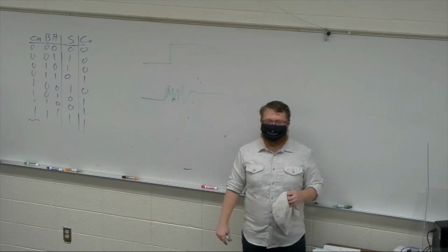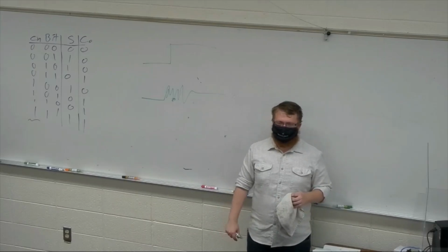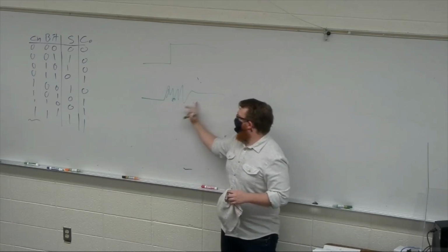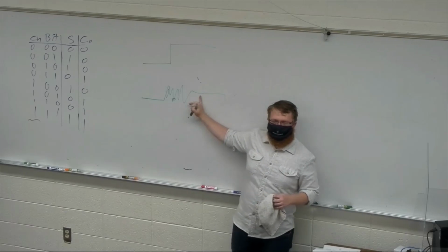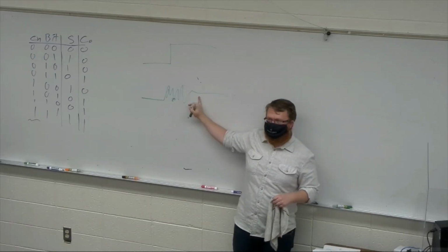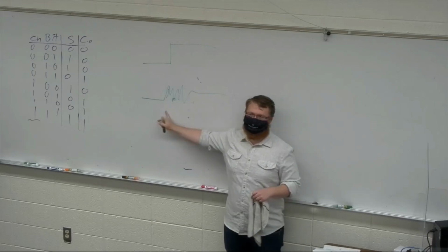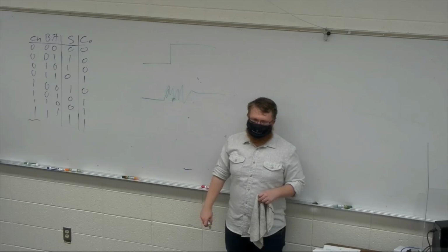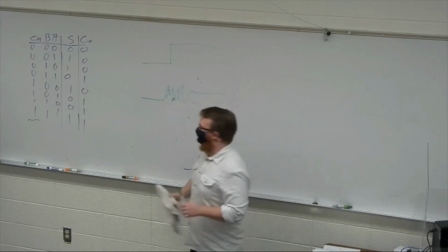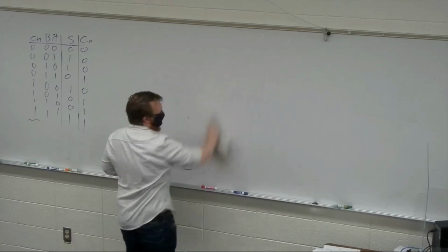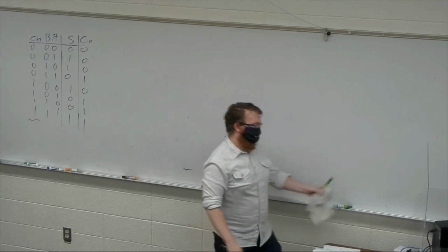Can you also sample such that you won't have an issue? Well, that's what the two methods are doing, they're methods of waiting until a certain point to sample. And your data sheet for the switch should have information on its maximum bounce time. Switch data sheets are awful, I will tell you this. They're not very consistent, but it should have that. And if not, if you're at a big company, you'll have access to a mechanical engineer and they'll tell you the answer.